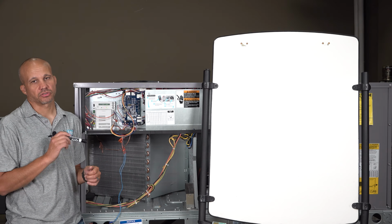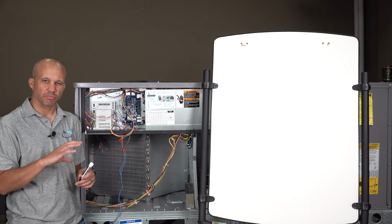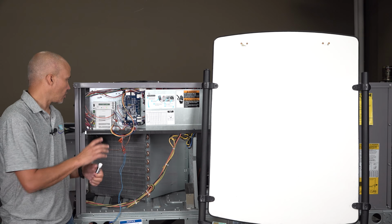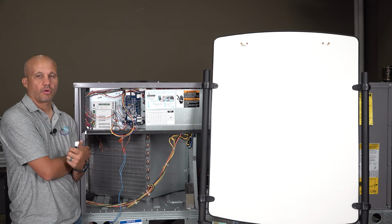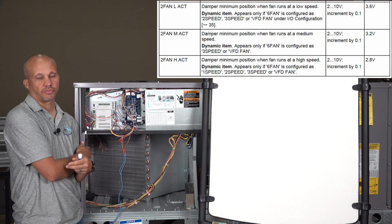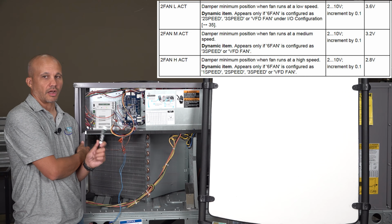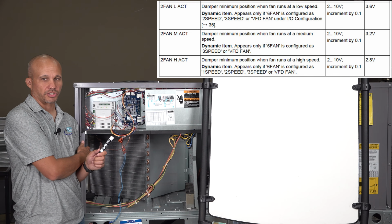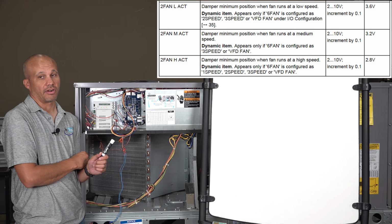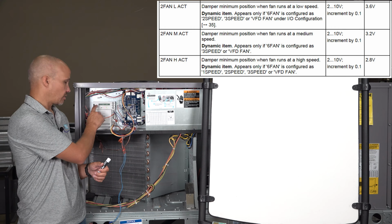Before we go into the actual advanced setting screens on this Siemens controller, I did want to finish up a little bit something on the basic setup screens that is a little bit more confusing and more advanced, right? So we have the fan low actuator position for minimum ventilation, and we have the fan high actuator position for minimum ventilation. And we talked about those in the previous video. We said that you can have different for CO2 and multi-speed fan and all that stuff. The hard part, though, is that all of these minimum positions are not in CFM, and they are not in percent damper open. They are in voltage, and that confuses a lot of folks. So I want to cover it a little bit.